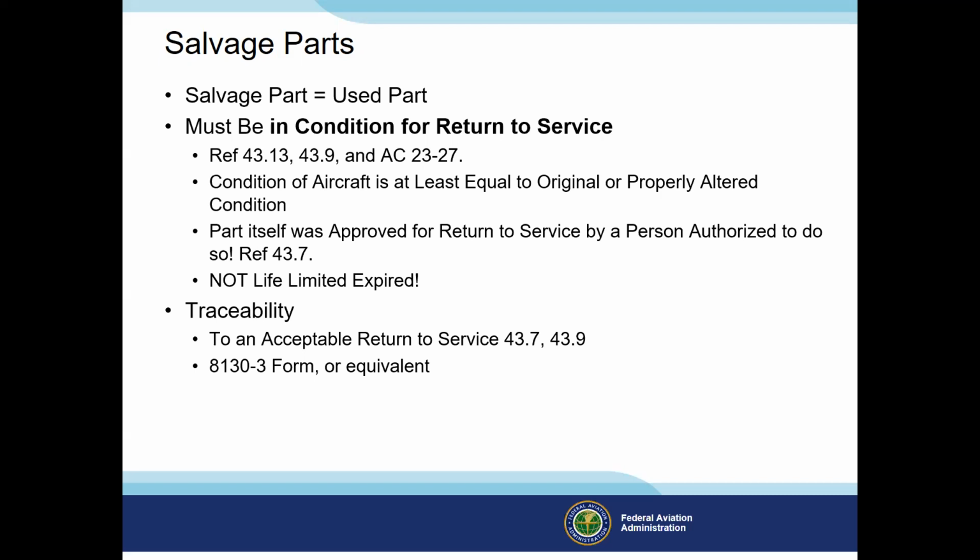Also, make sure the part has not met its life limit. There should be good documentation on all life limited parts. As far as traceability, just a packing slip saying that this particular part is what is in the box doesn't mean it was returned to service by an appropriately authorized person.